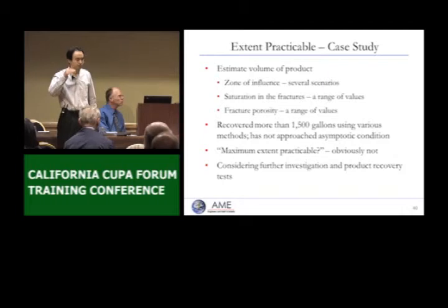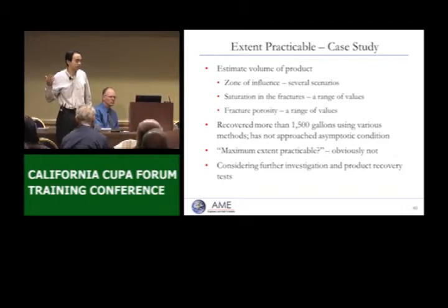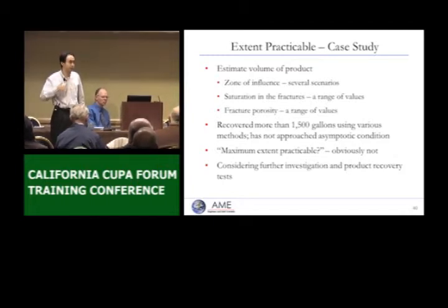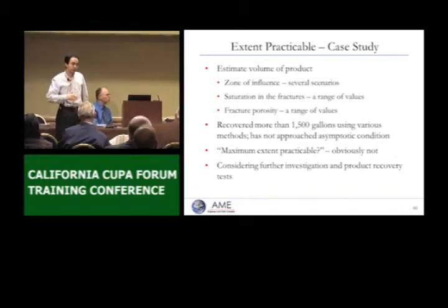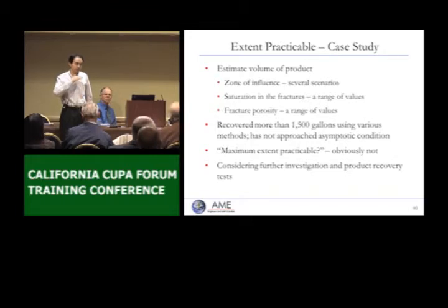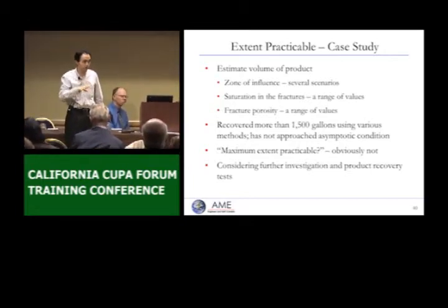The water may not be under pressure all the time. Historically, if you pump too hard or with water table fluctuation, the potentiometric level could drop well below the base of the aquifer. In that case, the confined aquifer becomes an unconfined aquifer. So the oil is free to find a hole in that layer and flow on top of the water table. And then with time, when the water level recovers, the whole thing becomes under pressure. Then that happens.